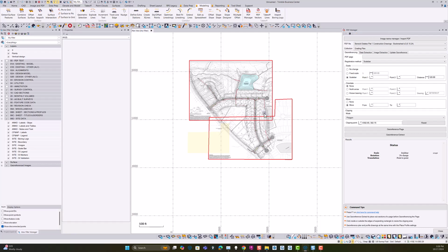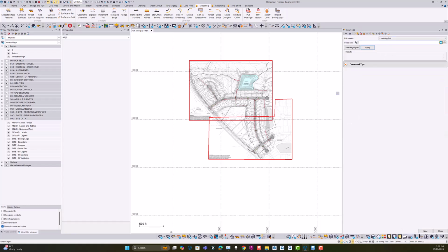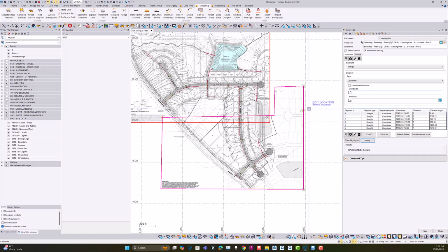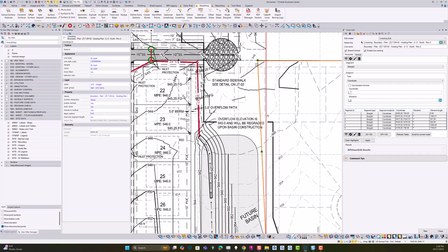and in the smart edit function it's going to open up, and I'm going to pick the line string edit function out of there, and I'm going to say pick the line, and I want to edit this line right here. And now I can press Shift M to turn on a little menu and pick rock grips from the menu, and now I can start grabbing this here, and I can grab this one and put it over here somewhere.